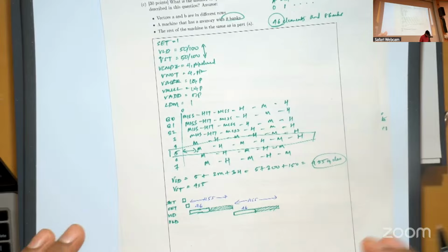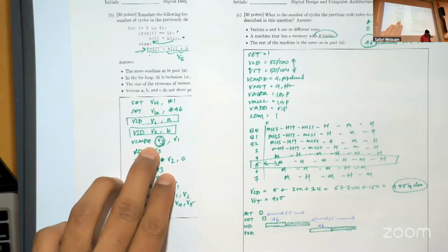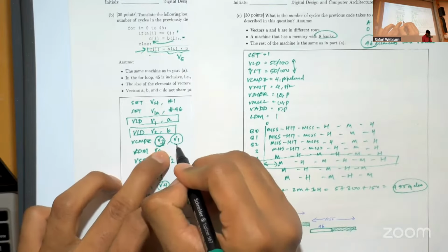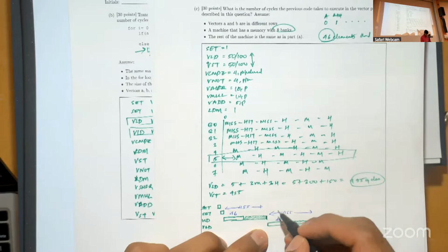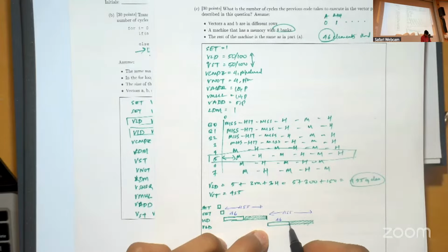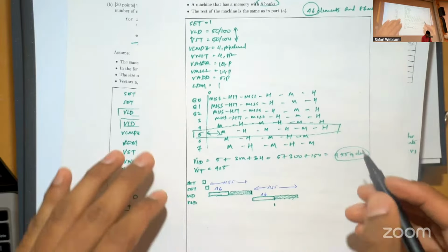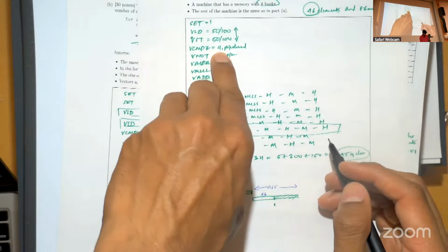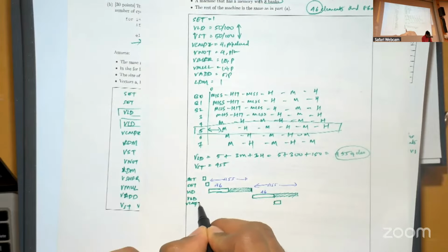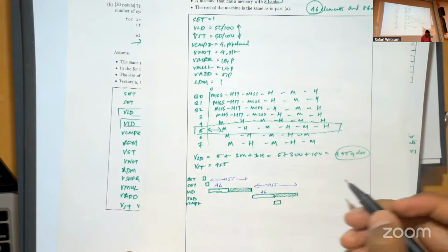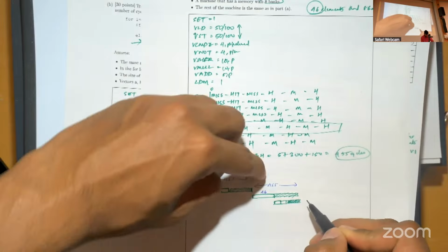And after the VLD instruction, you have the vCompare to 0 instruction, which relies on one input, V1. And the data for V1 is available already at this point. So after the 46 cycles have been spent, you can start the vCompare instruction. The vCompare instruction takes 4 cycles to start off, and then it's pipelined. So this is the 4 cycles it takes to start. This is vCompare 0, and then it's pipelined for 45 cycles. And it will be hidden behind this because this is 455. It's going to be much longer.